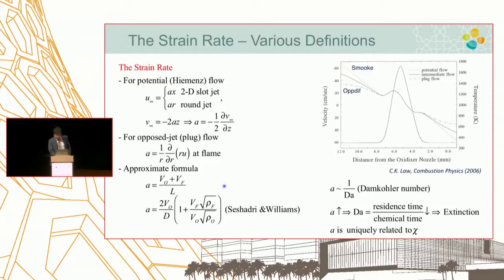For the real burner system, this can be done again following that track, because the difference between the two is that at the nozzle exit, the velocity is not perfectly plug flow. You may have some divergence of the velocity coming out. Chemkin's opposed-flow code actually allows you to have the tangential velocity value as finite, although if you want to match with the experiment, you need to know exactly what those are.